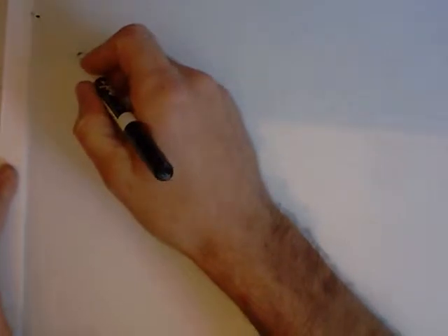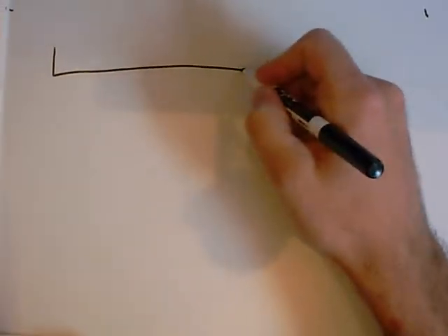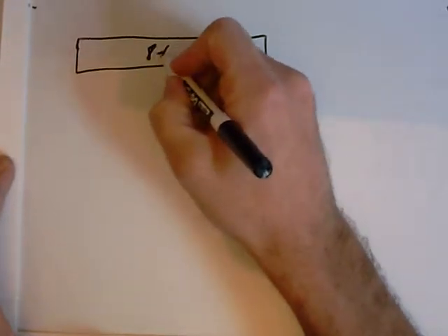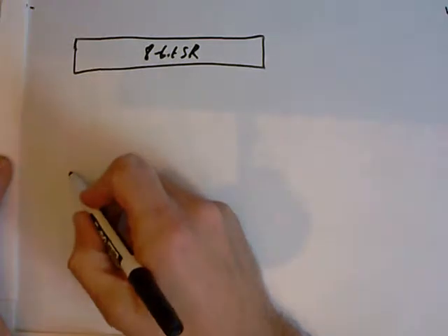So if we want to do a complete example here, let's go ahead and just build a Fibonacci generator on a cell matrix. And we're going to do this in pretty much the most straightforward way possible. We're going to use the shift register circuit that we already designed. And I'm going to use two shift registers. So this will be one, and this will be, say, an 8-bit shift register. And we'll put another one down here.